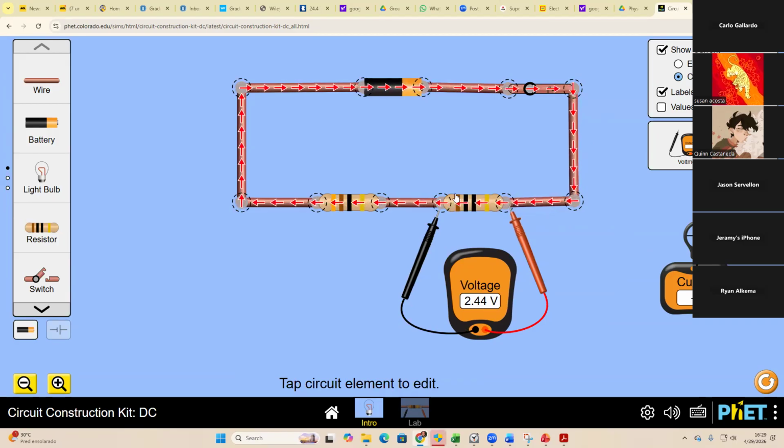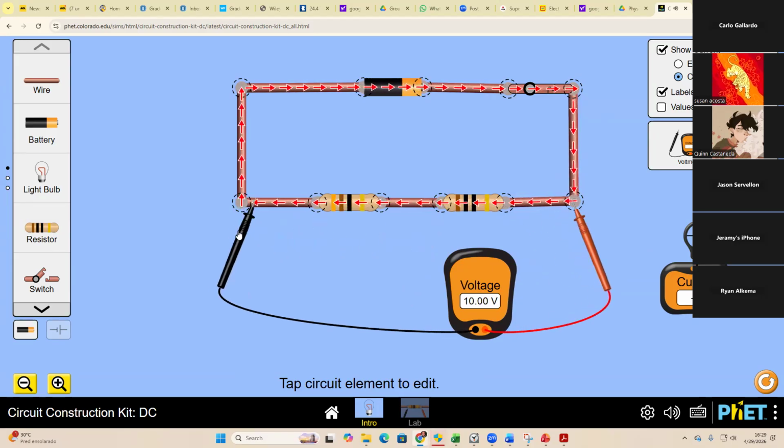That's why you're supposed to get the slope equal to R1. When we did it for the V total, right? The multimeter was in parallel with the two resistors in series. That's why we're getting a slope equal to R1 plus R2.